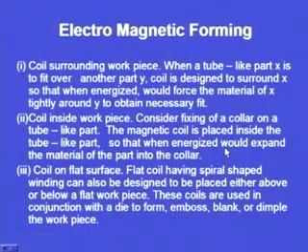So, whatever part we want to provide inside the collar, when energized it will expand the material and form a part of the collar. Now, the third case is the coil on a flat surface. There is a flat surface and there is a coil. A flat coil having a spiral-shaped winding can also be designed to be placed either above or below the flat workpiece.